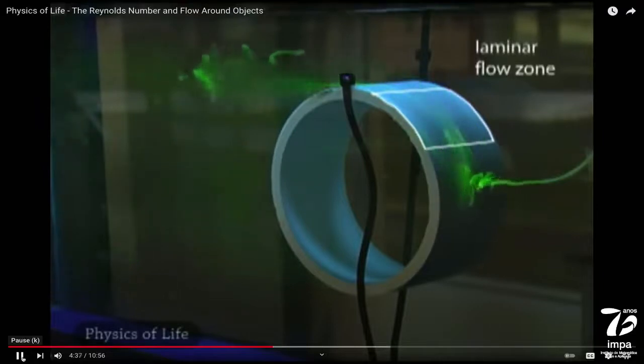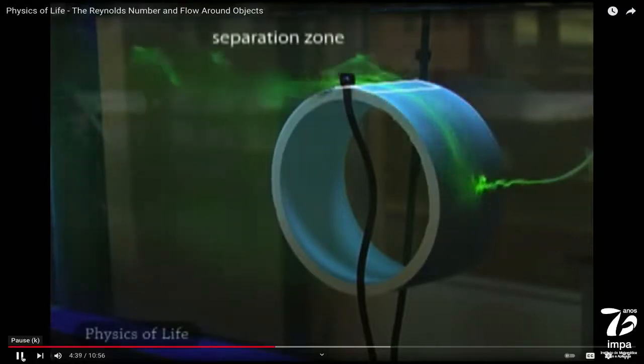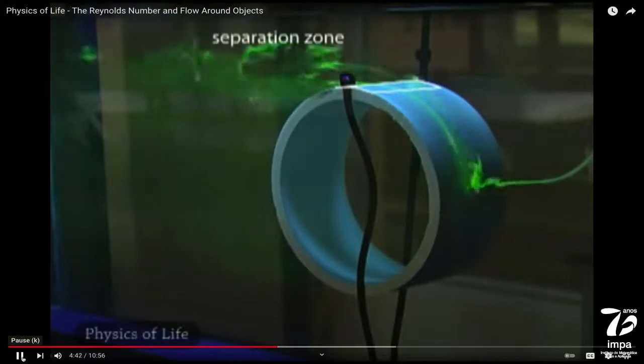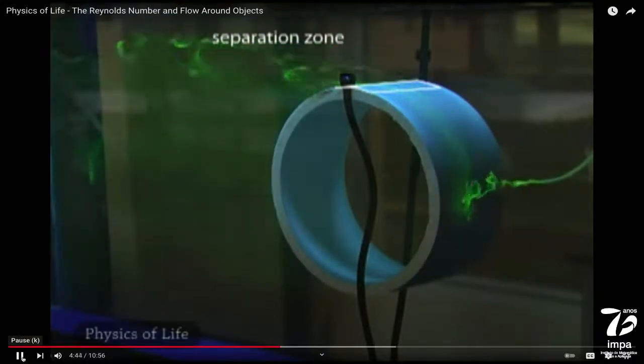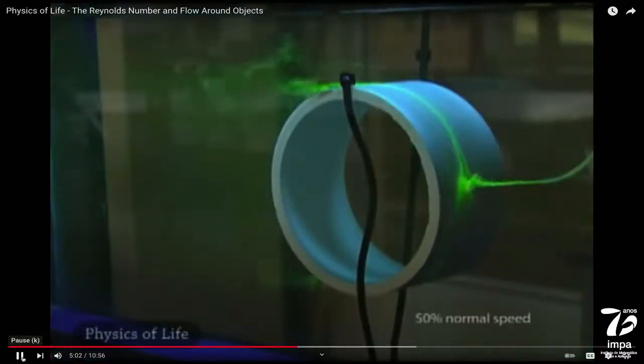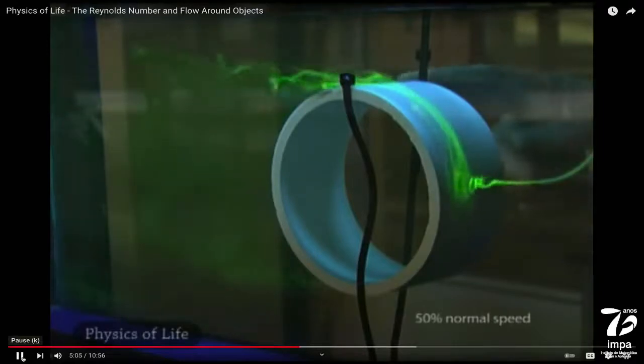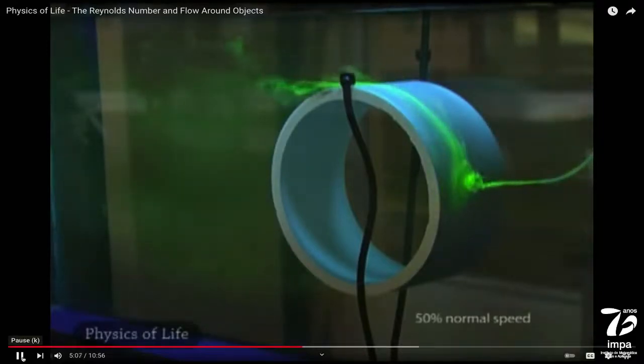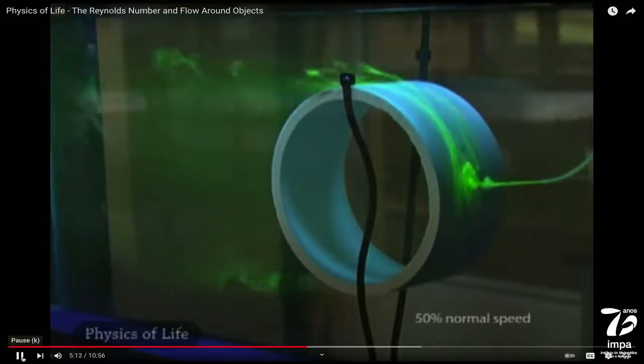Finally, just behind the cylinder's lateral face is a so-called zone of separation, where turbulent vortices are generated as the laminar flow just upstream separates from the cylinder as parcels of fluid in rotational motion. The separation occurs in part because the fluid behind the cylinder's trailing edge actually is moving in the opposite direction to the prevailing flow. When this retrograde flow encounters the prevailing flow, this imparts the rotational motion to the fluid, which separates as a vortex. The retrograde flow also produces a zone of relative stagnation behind the cylinder, seen in the accumulation of dye there.